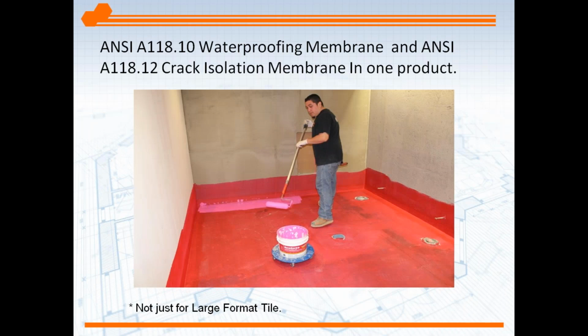If you take a look at the installation, this happens to be a liquid applied crack isolation membrane, and it has the dual purpose of being a waterproofer as well. And that's why we kind of highlight it in this presentation. These liquid applied crack isolation membranes also offer waterproofing and vice versa.